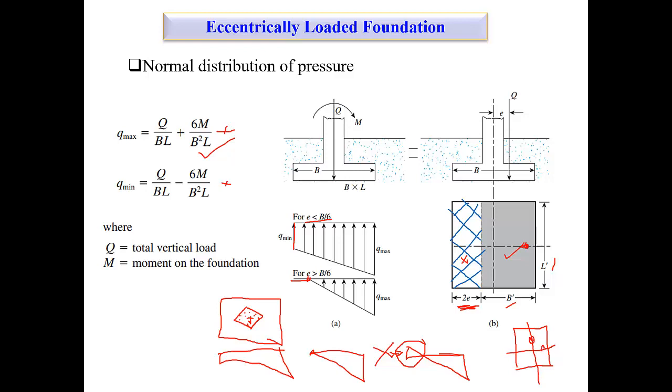But if you consider the load in the opposite axis, suppose you have a load here, before you had a load in this axis. Now you are considering this part, so maybe you will have a cut like this. So this portion is ineffective, right? So for y-axis eccentricity, it is just opposite. You need to think, if you apply the load there, which area might have the tension, and that area you try to skip, but you have to follow some guideline to do this.